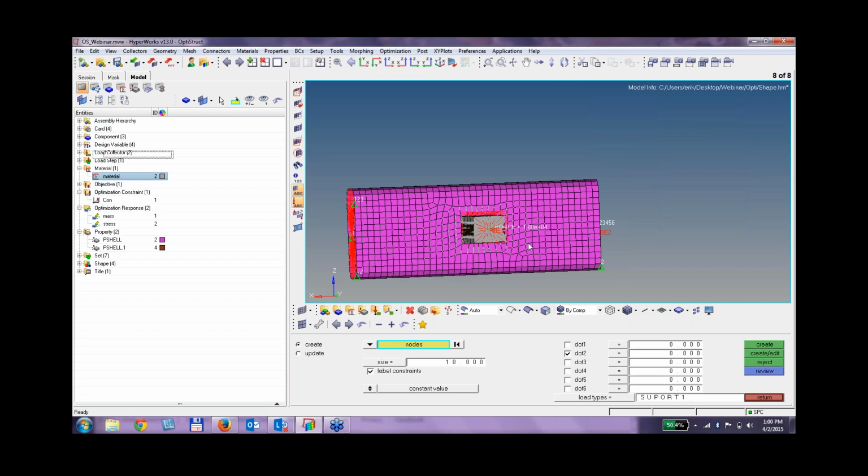In general, where specifically you put them doesn't really affect the analysis. It may make the deformation look a little bit different because it changes your frame of reference for the deformation, but your results will be the same, irrelevant of where you put them. Just find 3 points at extremities of your part, put 1 at 1, 2, 3, move in a direction, remove that direction, move in the third direction, remove that direction, and it will always give you 6 degrees of freedom properly oriented.